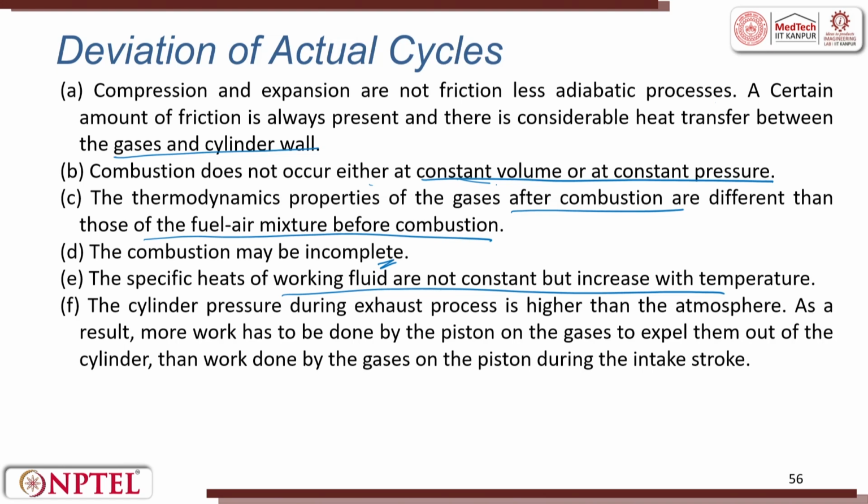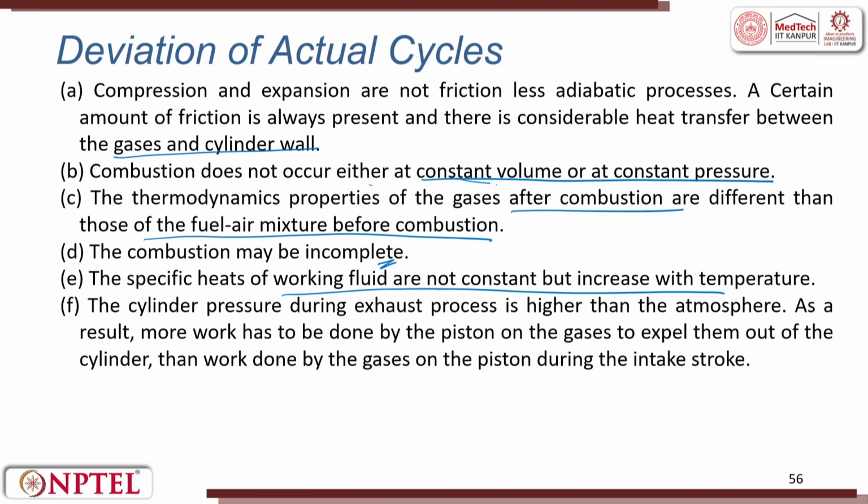So now people are trying to use glass engines and see the combustion, how it is happening, how it is propagating, through laser. They are trying to monitor very precisely, but still it cannot be found out by one laser. So they have lasers in multiple planes. In one plane they try to take the temperature distribution and see how the wave propagates. So that is a challenge. Even now there is a lot of work going on, and big auto industries work on how to improve the efficiency of combustion.